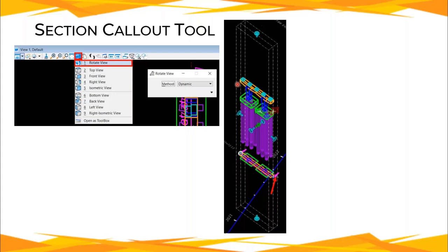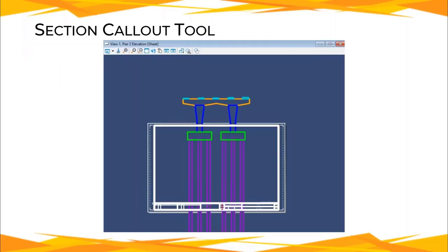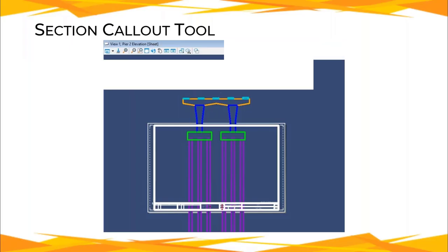This is what is containing the 3D elements and what I want to show in that 2D design model. So in this case, going back a slide here, I need to cut off these pile. I don't want to show 80-foot pile on my sheet model here. I can just cut these off somewhere below here, and that's what I want to show. I can move this whole pier down, and that'll be what I want.